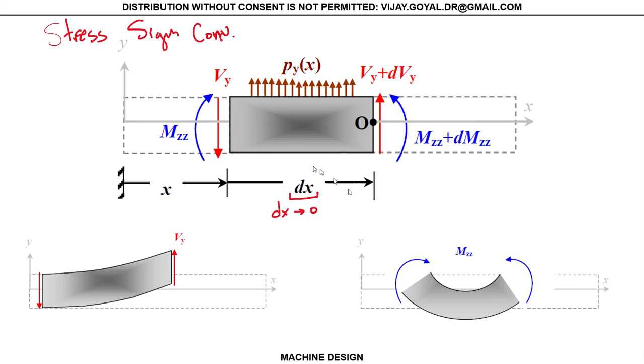So with that said, because this is an elastic material, my loads cannot be the same. There has to be some differential of that load, and the same thing, there has to be some differential of my moment. This is because it's elastic. Okay, this is the consequence of being an elastic material. If it was rigid, then the loads would have to be identical. Think about a case in which this is acting as rigid, so all my loads applied here are completely transmitted there.